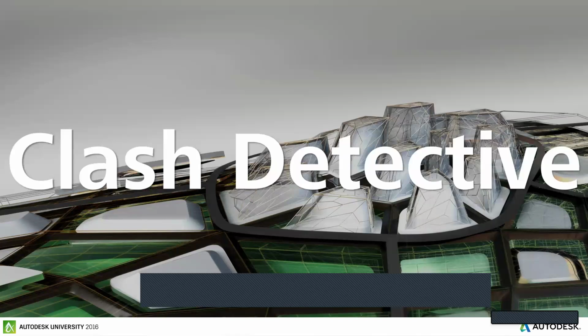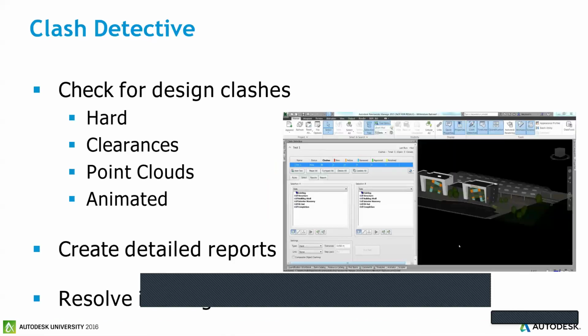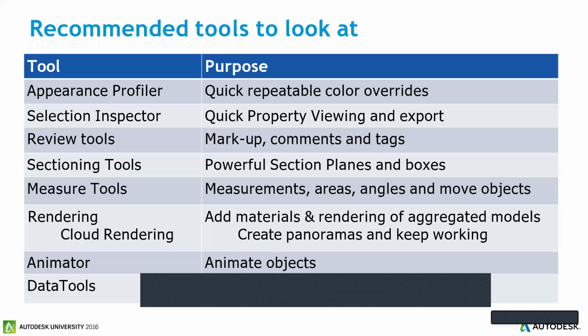Coming back to the part of clash detection, this is how clash detection works. You need to specify the tolerances, you need to add the test. First step is to add the test, that is, between which models, and which all the other models of disciplines. So you need to select those models, set the tolerance limit, and then you can get the clash report as well, the number of clashes, and you can export the clash report in .html format. Right.